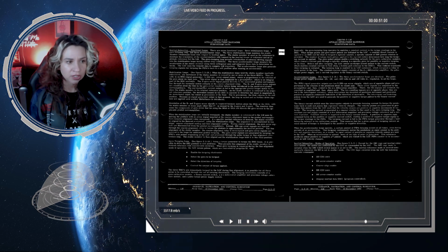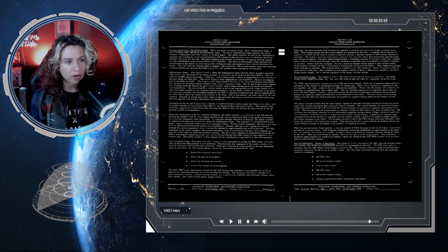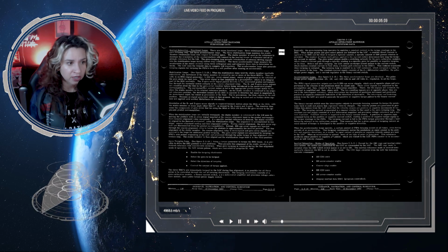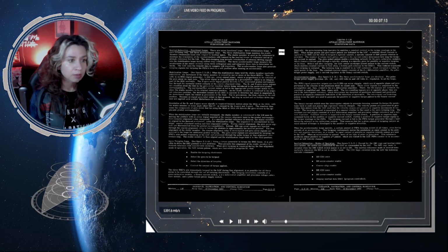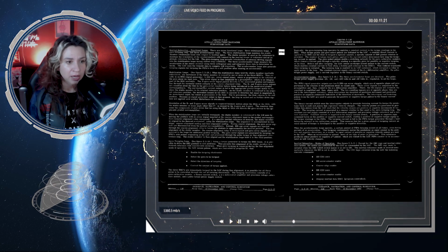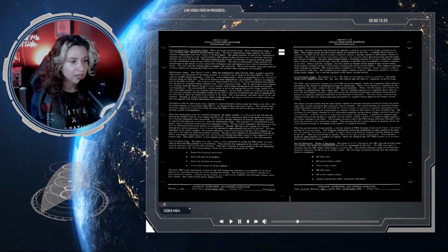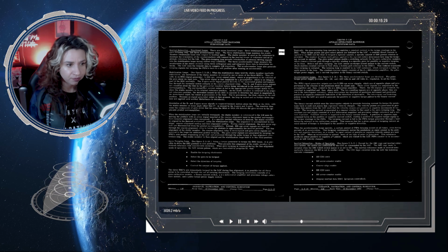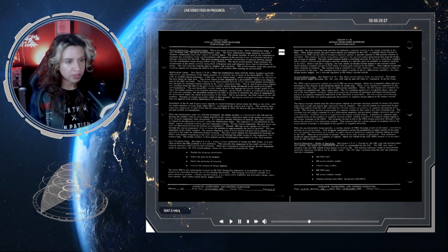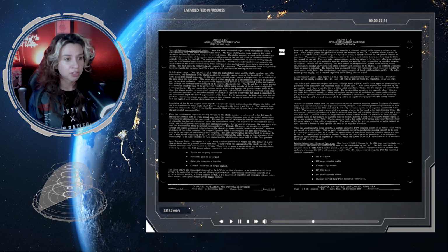When an acceleration is sensed, more of one type of pulse is generated. This unbalance produces either positive or negative delta-V pulses, which are routed to the LGC PIPA counter to be accumulated as LM velocity changes. The inertial subsection modes of operation, see figure 2.2-11.